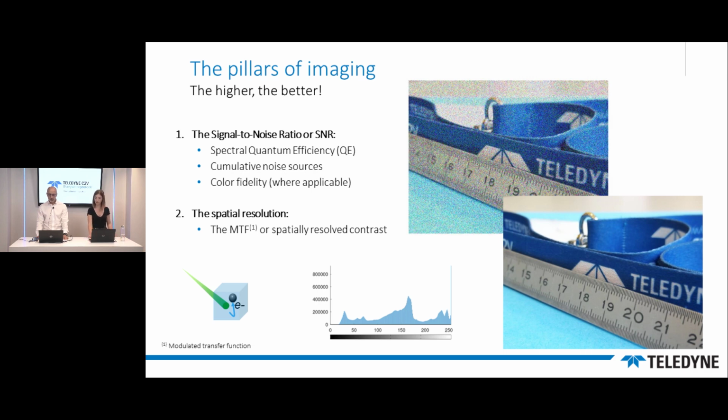So the pixel pitch becoming close to the wavelengths, some effects become important, such as diffraction or perimeter effects, optical or electronic crosstalk, and so on. So the arrangement in large pixel arrays increases the difficulty to make these characteristics uniform throughout the whole image.